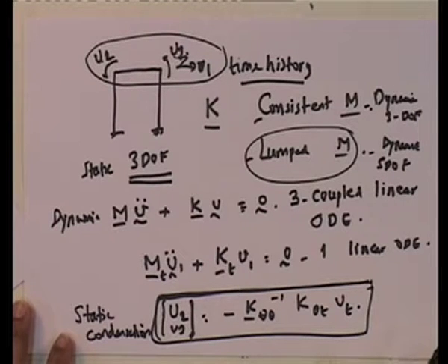The advantage of the consistent mass formulation is that whatever frequencies you get, you know that they are upper bounds. If you solve the free vibration equation using the lump mass formulation, you cannot say that the frequencies you get are upper bounds. They are close to them.